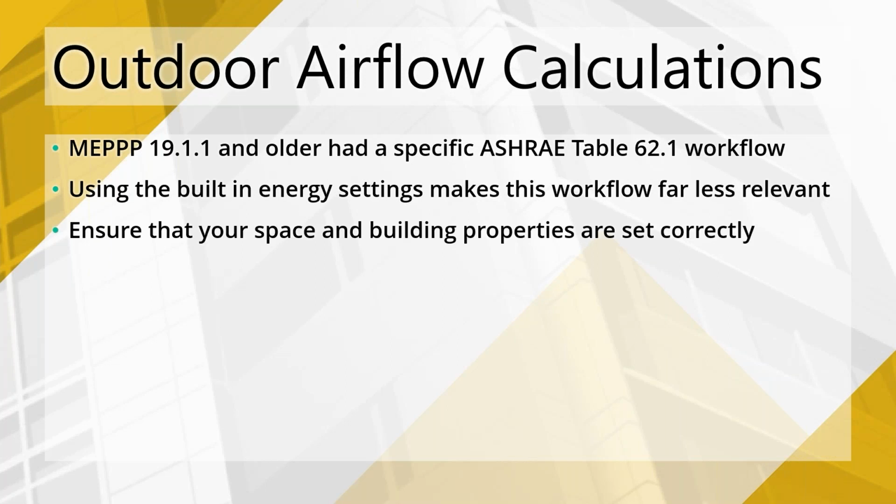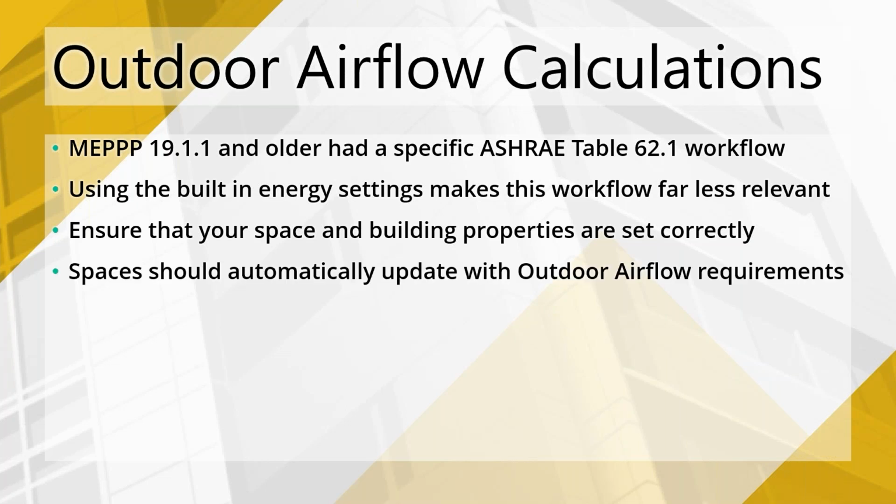The big thing is that you need to make sure that your building and space properties really are set correctly. We talked about that earlier. Some of those air exchanges, some of those outdoor air infiltration properties in those space settings, if you have those set up correctly, when you're applying your space type for your supply air calcs, it'll also give you a number of the calculations for your outdoor air as well. So then technically, it should automatically update with those outdoor airflow requirements.